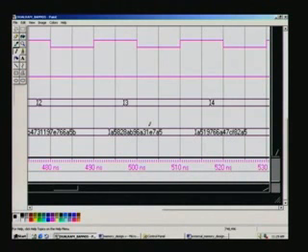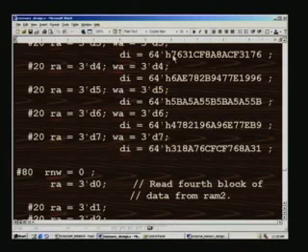So we are writing row wise in this order, so 64 bits are written straight away there. While reading, in the conventional memory, when you give a read, you will get only this row wise, right? Whereas our requirement is not row wise but vertically. This is because of the algorithm that I have developed for DCTQ which demands this. So, I can't use the conventional memory, and that is the reason why I went for a specialized design for this, right.